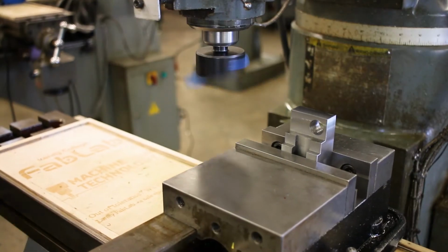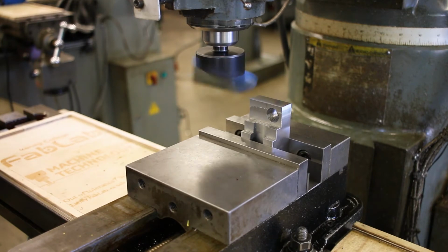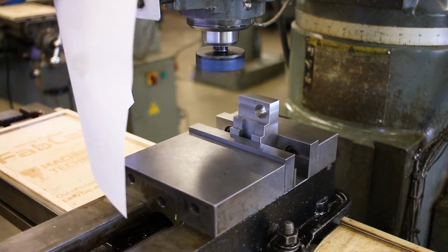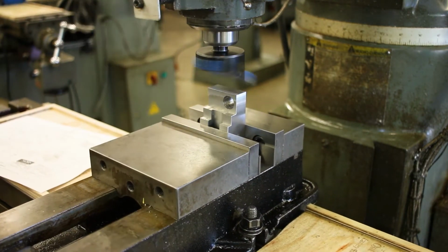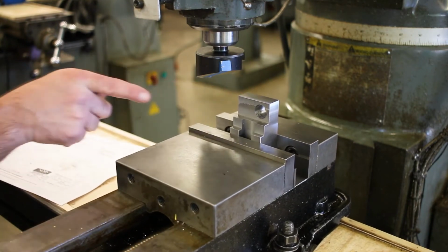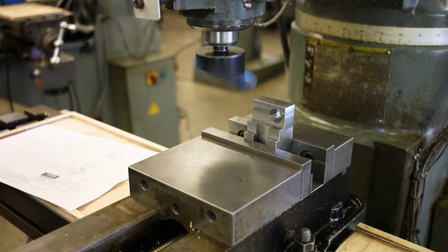Turn it back on. Come back to the start of the cut. All right, go in 10 thousandths from where I am right now. Okay, take that cut. Back to the start of the cut. Remember, we only like to cut going one way with these. Turn it back on. And then another 9 thousandths.